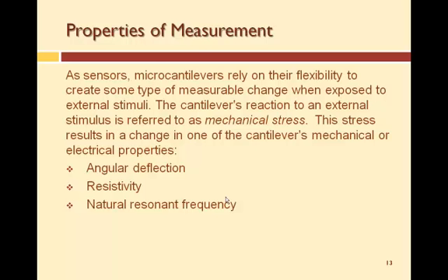If the coating contracts, it's going to want to bend in the opposite way. It's going to want to pull the meter stick so that it bends in this fashion. Right? Does that make sense? So either it will bend up or it'll bend down, depending on if the coating's going to want to stretch or contract, expand or contract.